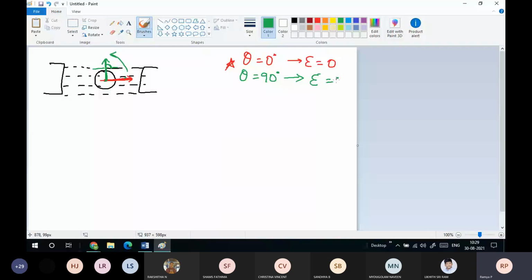When you go on varying this conductor rotation with respect to time, when time t is equal to 0, my conductor was in the 0 position. When time t is equal to 10, the conductor is in some position making an angle theta of 45 degrees. If it is 45 degrees, I am going to get BLV into root 3 by 2. For the next increasing angles, I am going to get a complete sine wave like this. A complete 360 degrees I get like this when the conductor is moving. What is this? This is a sinusoidal wave.